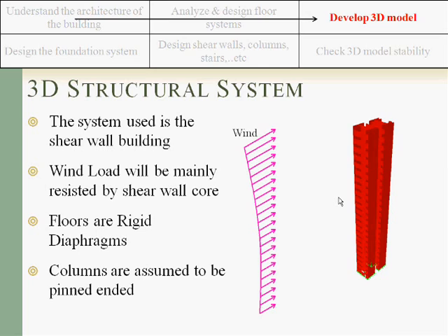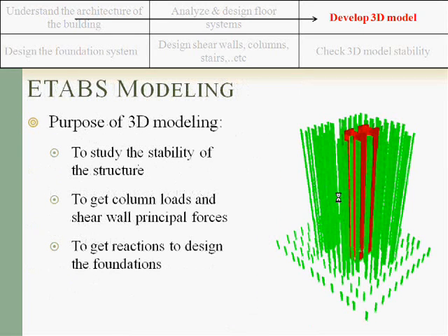This assumption is discussable, but some of the professors agree to assume concrete which is not detailed with special detailing as pin. If some structures need special detailing for rigid beam to column connection, I will present it in a different presentation, but assuming a pin column is more conservative.